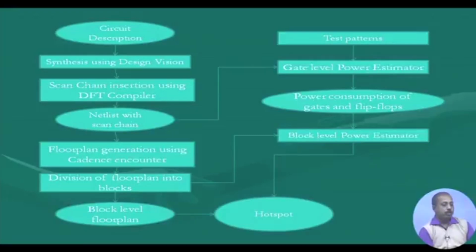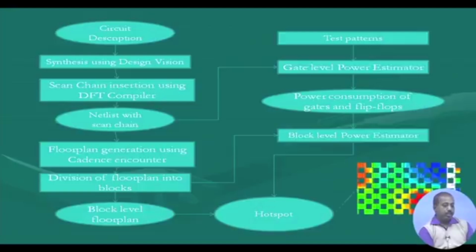Now we have got these two: the block level floor plan and the block level power estimator. They can be fed to some thermal estimator tool such as HotSpot, and then it can give us the temperature profile.